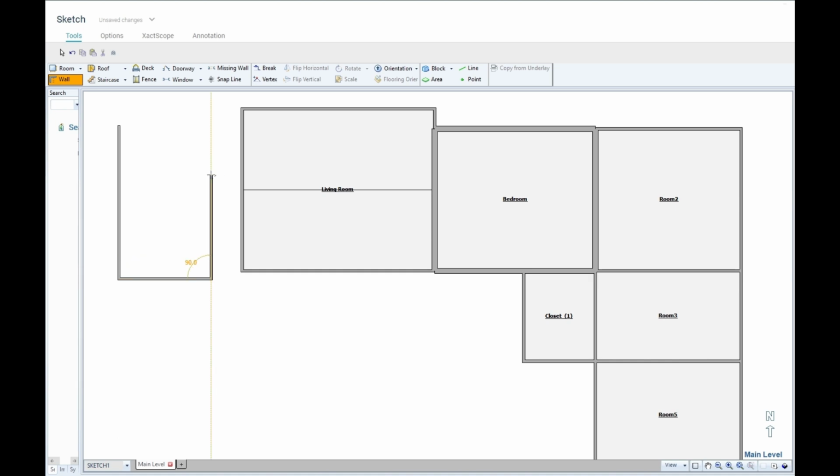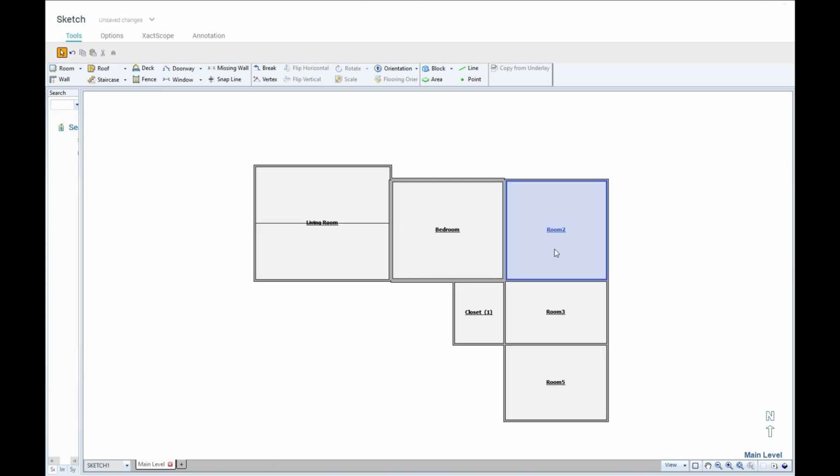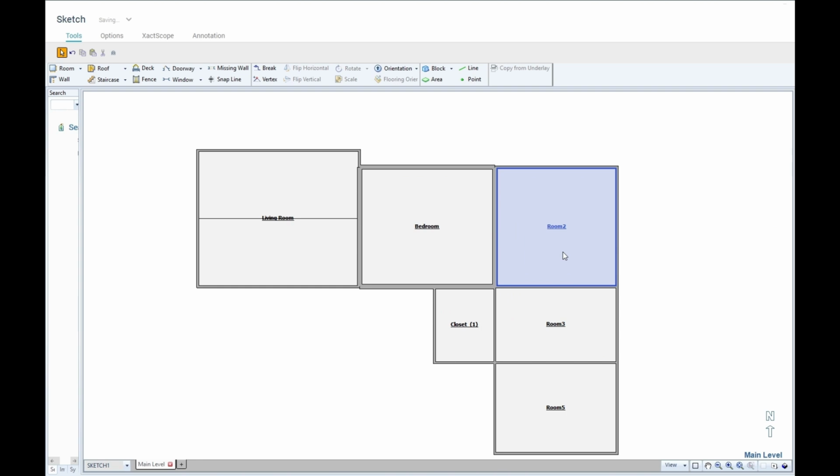Select the tool, then hover over where on the wall you would like this wall to protrude from. As you will see, when you click to place it, the wall tool is still active. In order to drop the tool, press Escape on your keyboard. As I mentioned, this tool you will mainly use for things like pony walls.